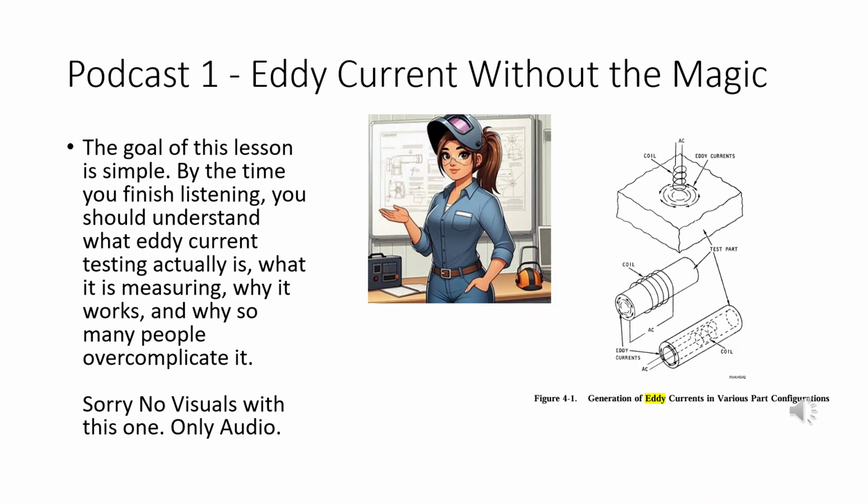ET is a signal-to-noise game. Let's introduce another concept, signal versus noise. The flaw creates signal, everything else creates noise. Probe wobble, surface roughness, edges, geometry, fasteners, paint, temperature, material variation, all noise. The inspector's job is separating signal from noise. That's the real profession, not operating the instrument.